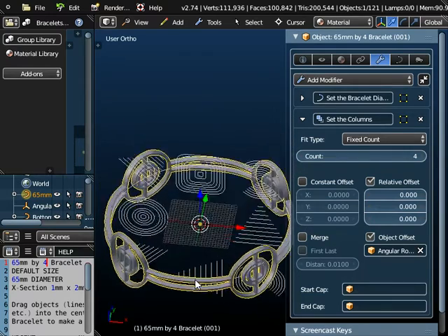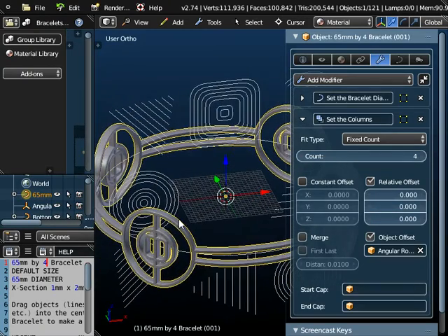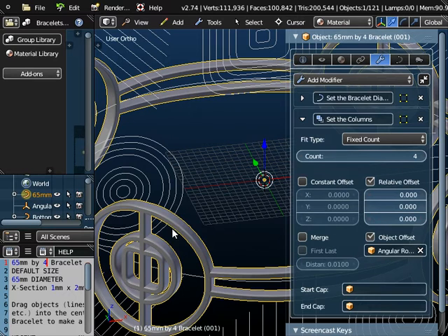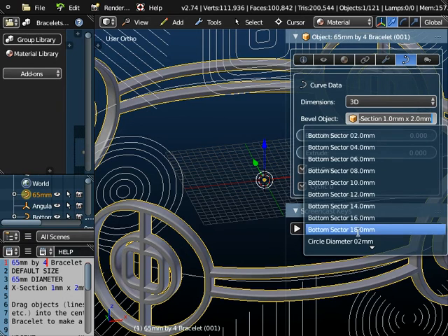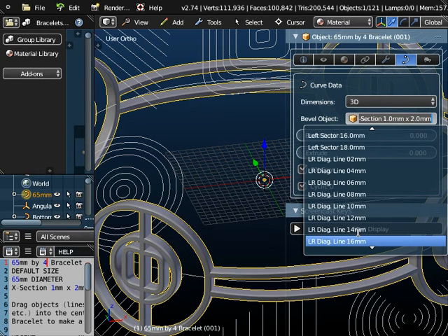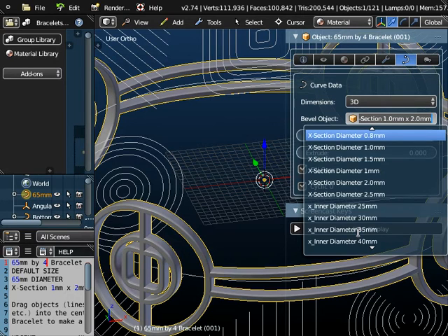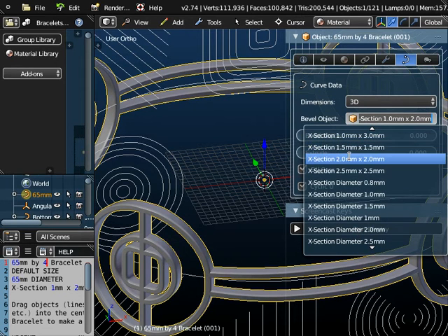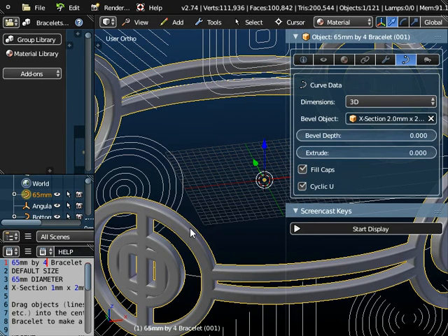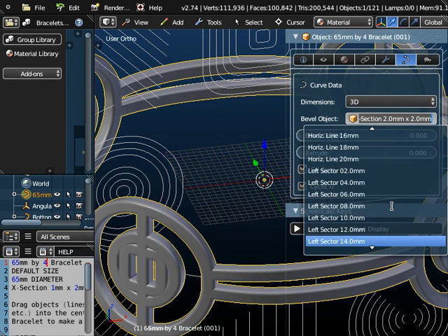and this will in fact 3D print because it's got a thickness of 1 millimeter here and a depth of 2 millimeters. And again, like we've shown you with the other objects, we can change that. Unfortunately, it's all the way down at the bottom here because there's a lot of objects in this particular file. But if I go all the way down to the bottom here, yeah, I can change my wall thickness. So I could change it to 2 by 2, for example. You'll see that makes it 2 millimeters by 2 millimeters. Not quite as attractive, so I'll just set it back to the 1 by 2 that was there.